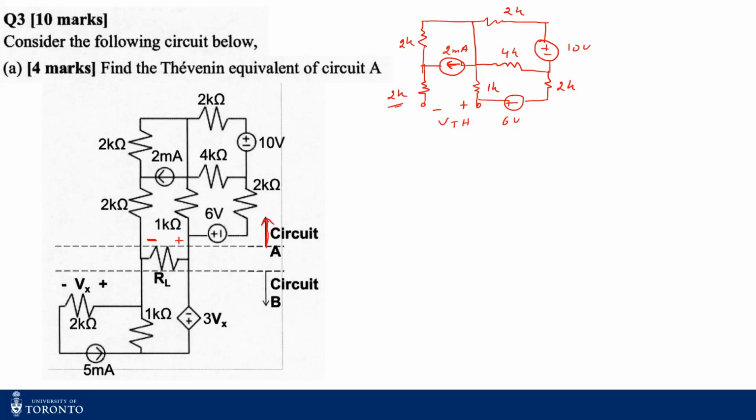So I have to find out this Vs and this V1, let's say. Then I have to apply KVL. If I apply KVL, I will get VThevenin plus Vs plus V1 equal to 0. So from there I can find out my VThevenin once I know the voltage across the current source and the voltage across the 1 kilo ohms resistance, right?